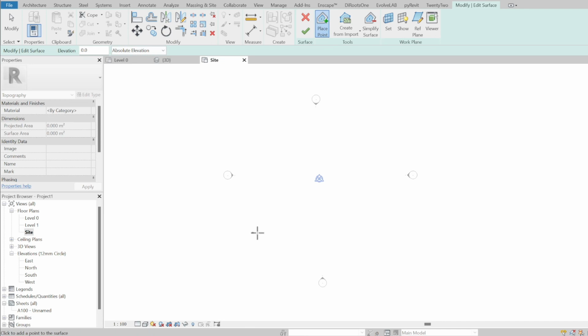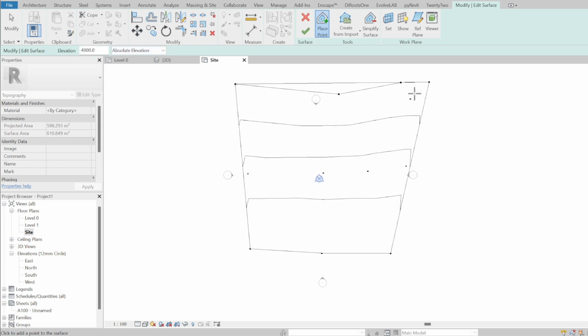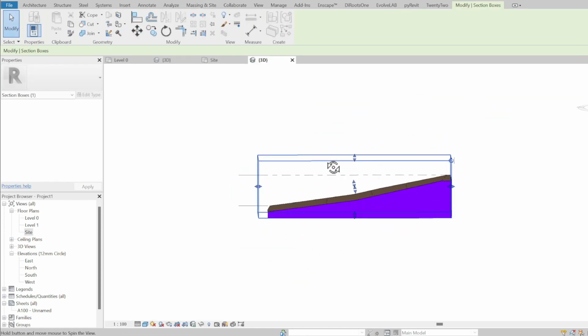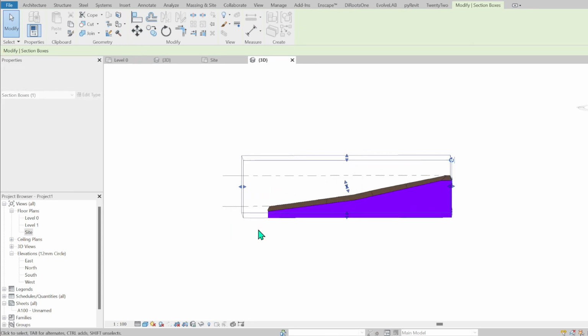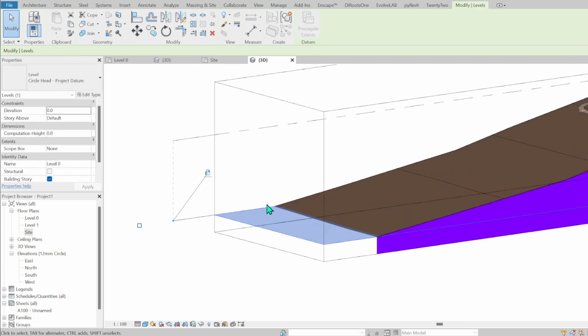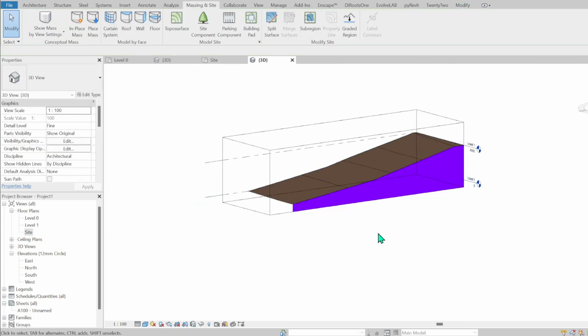I will start just by putting some 0 points here. And then I will say, okay, let's raise this land by 1.50 meters. And then I decide, okay, let's get crazy, let's put 4 meters. And I place here 4 meters. When I click on finish, I go to 3D and I see, oh yeah, I have created this land which is starting from 0 and going up to 4 meters. So this dotted line is 0 and up here it's 4 meters.